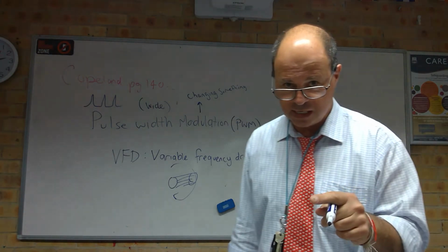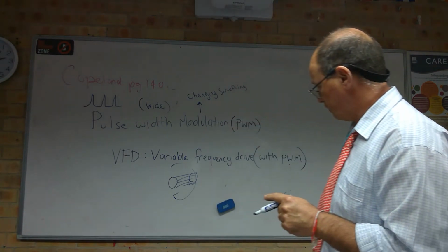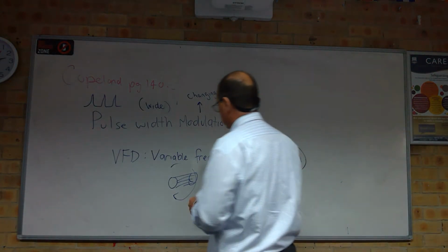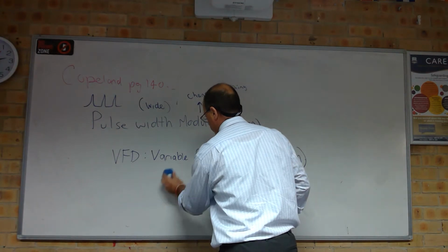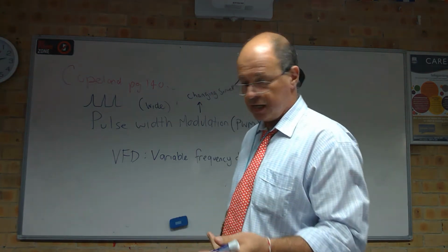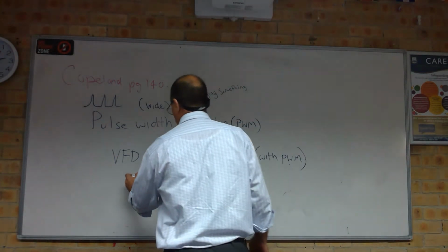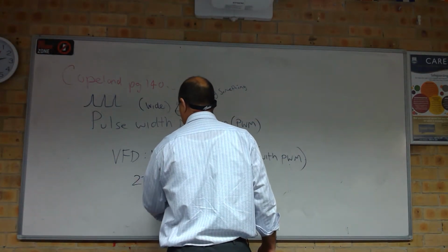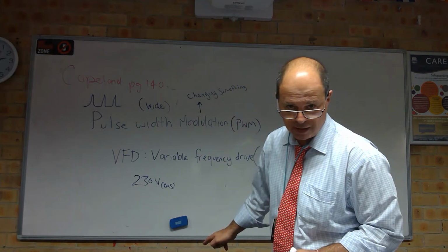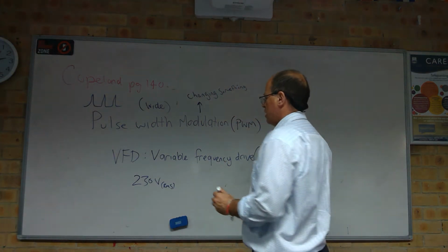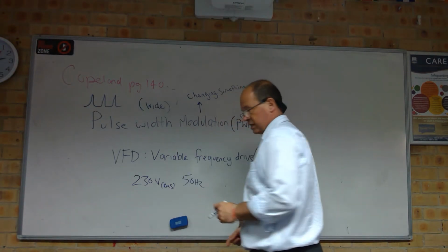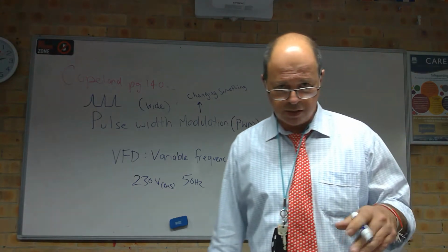that rotating magnetic field. But the trouble with an AC motor is the speed of the motor will be determined by the frequency that we supply to the motor. And in the case of mains AC voltage in Australia, we know that we have 230 volts, and that's RMS, root mean square, that's effective voltage. We talked about that when we did power distribution, at 50 hertz, which is 50 cycles a second. Now the motor doesn't spin at 50 hertz.